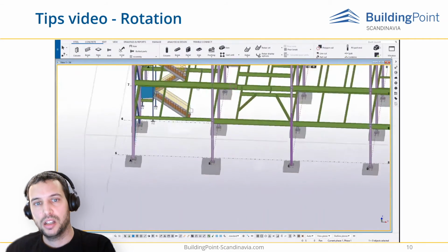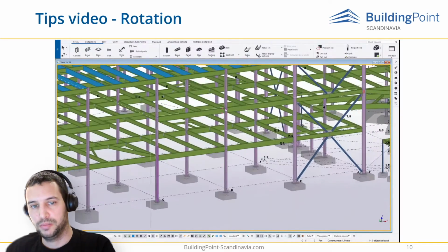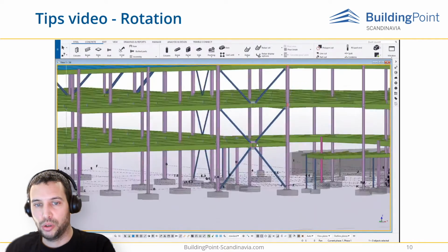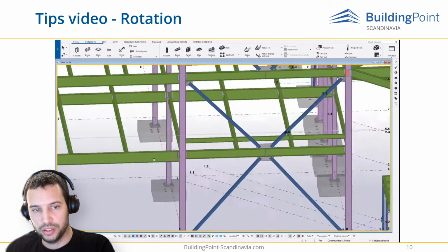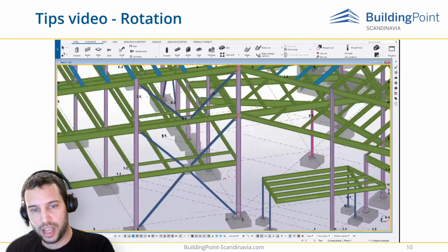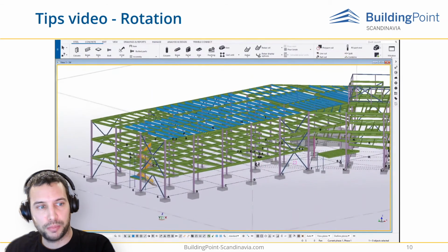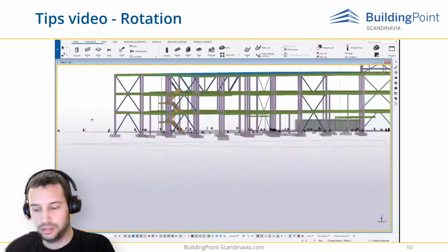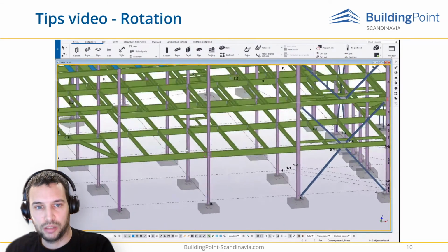And again here. One thing you need to be sure about is that you have to point at an object to get the most precise rotation. If you don't do that, you don't know where your point is actually being placed. Here I have it on the object, as you see. And if I try to press out here at nothing, it actually goes okay here because it's close to the grid. But if we go out a little bit further and press in the middle of nowhere, you see the rotation point is not that great. It's not beneficial. So press on an object to rotate, best way.